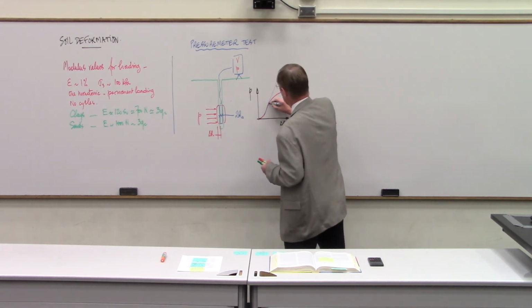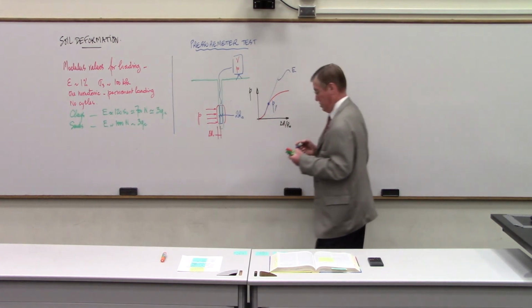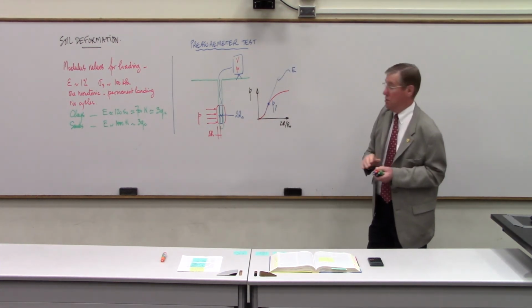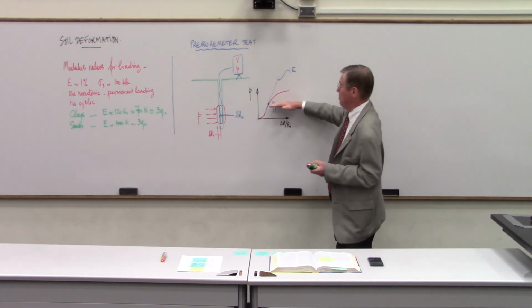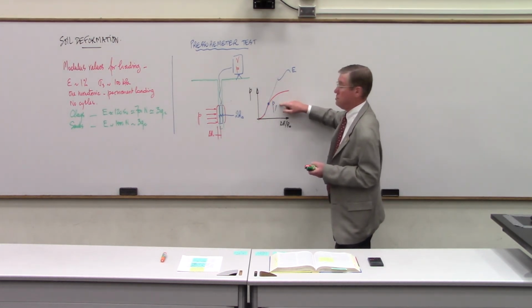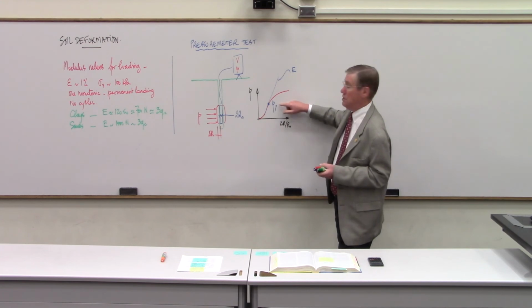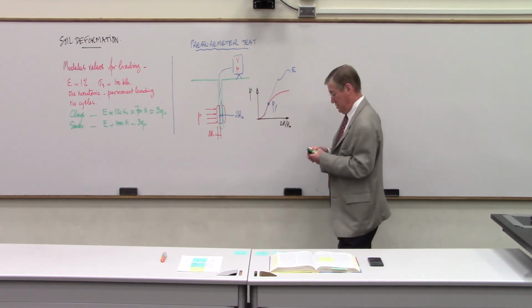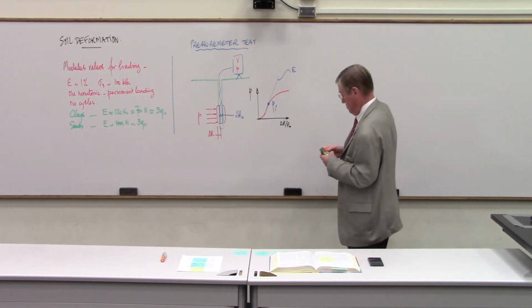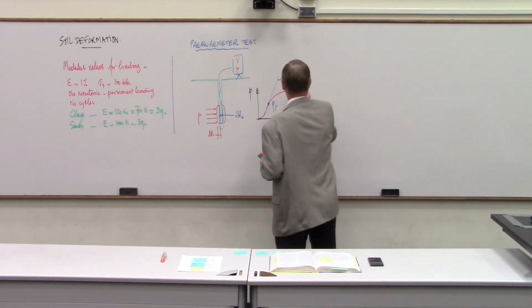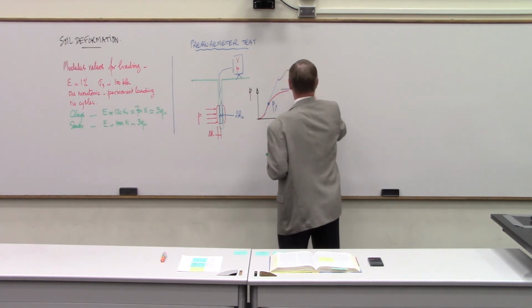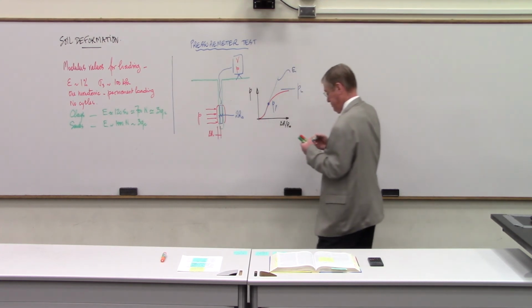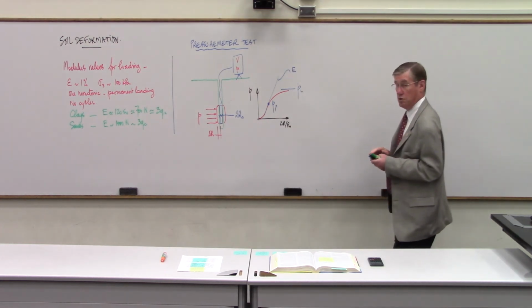Right here, you have a yield pressure, which will be very useful because you want to keep the loading of the foundation below this yield pressure so that you minimize the amount of creep and long-term movement that you're going to accumulate. And then right about here, you have what is called the limit pressure of the soil.